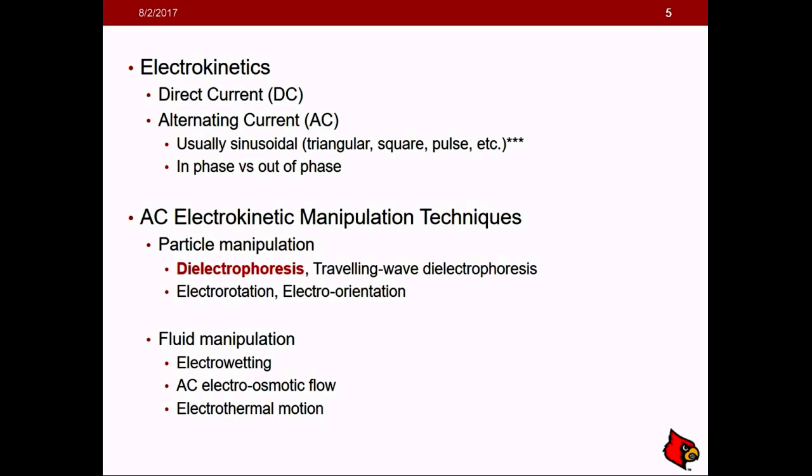Now we are focusing on AC techniques. You can do dielectrophoresis with DC currents, but usually when we talk about the theory and apply dielectrophoresis, it's a frequency dependent mechanism. And I'm going to focus on sinusoidal signals. I'm going to assume that when I talk, but you can apply square waves and pulses, etc.